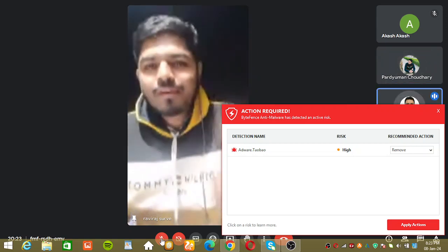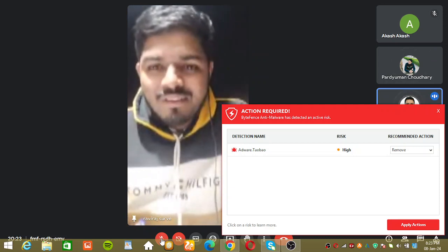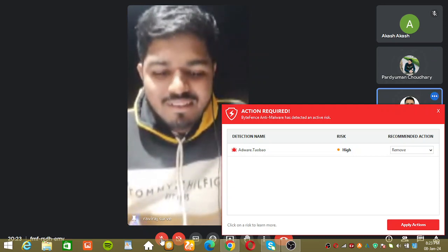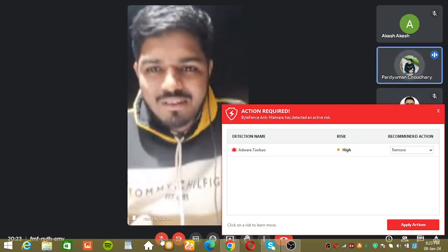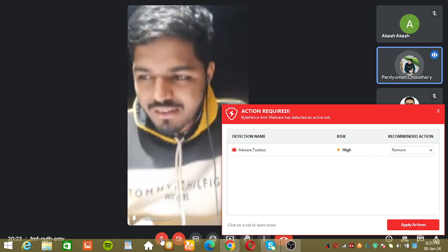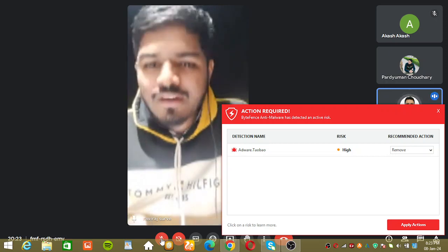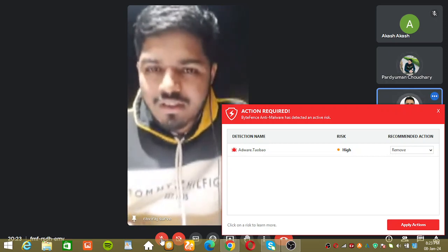That's the actual concept. When air gets compressed, the temperature of the air increases. To release that temperature, we use aftercoolers inside the compressor to reduce it. But if somehow the temperature does not reduce, we get an alarm. After that, the temperature switch gets activated. There's a high temperature alarm.